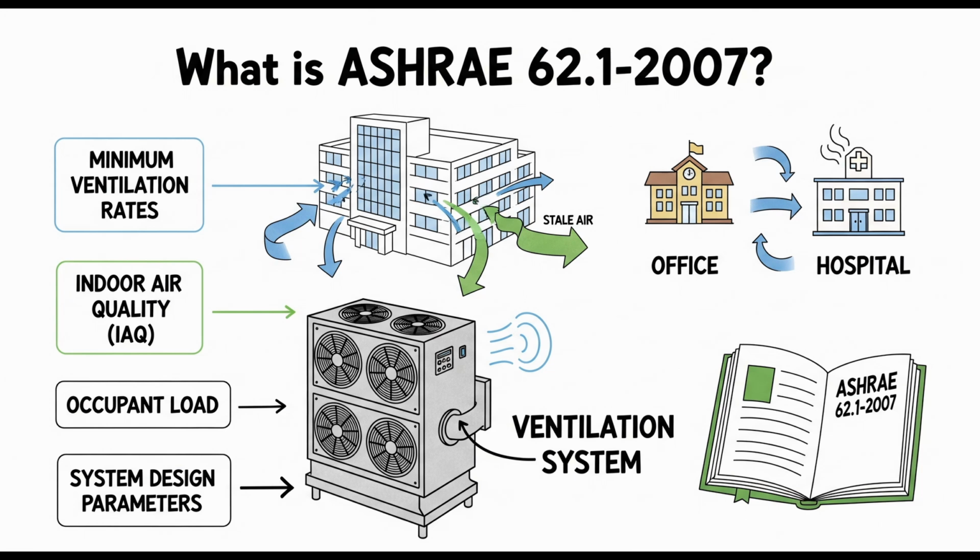Well, the building skin needs barriers to stop rainwater leaks, obviously, but also vapor barriers to prevent moisture moving through walls and condensing inside them. And it needs to be sealed reasonably well against air leakage. Why air leakage? Because uncontrolled leaks mean untreated outdoor air, plus moisture and pollutants, can sneak directly into the space, bypassing your filters and your controlled ventilation system entirely. Gotcha. So the building structure itself is part of the whole IAQ system, not just the box the HVAC lives in.